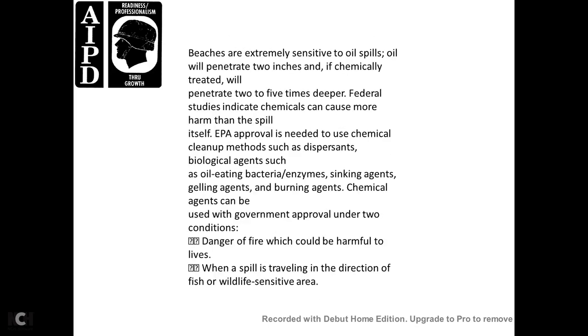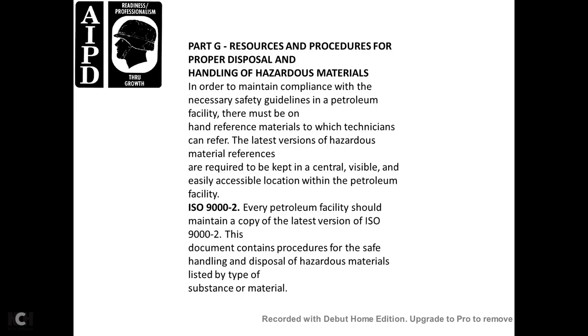Beach is extremely sensitive to the oil spill, but if it's chemically retrieved, the oil will penetrate 2 to 5 times deeper, and federal statute would indicate that chemicals can cause harm within the spill itself. Environmental Protection Agency approval is needed to use the chemical cleanup methods, dispersing biological agents such as oil-eating bacteria, enzymes, sticking agents, gelling agents, burning agents. Chemical agents are used with government approval under 2 conditions: danger of fire, which could be harmful to lives, and when the spill is traveling in the direction of fish or wildlife sensitive to the area.